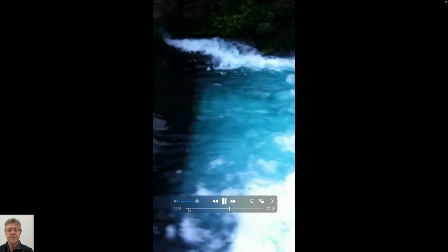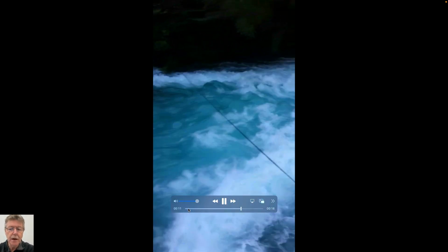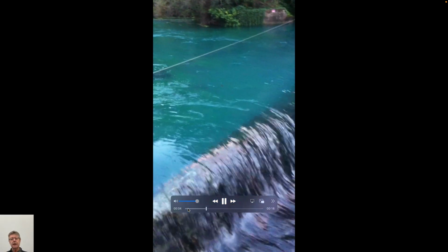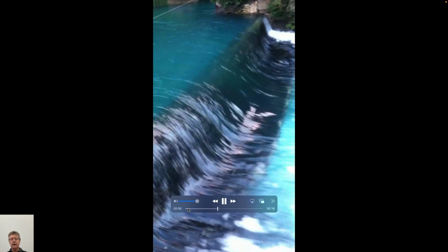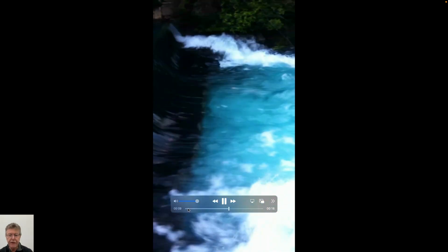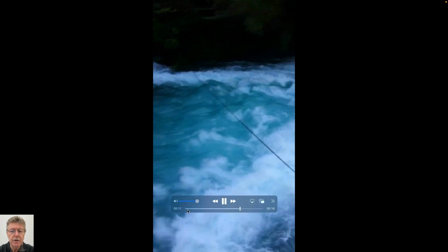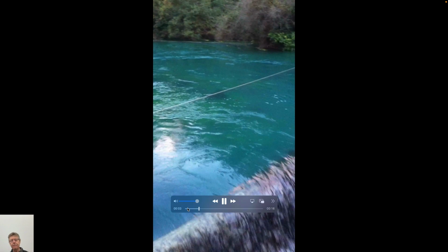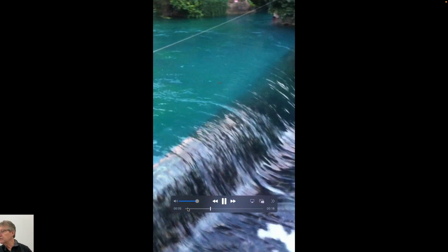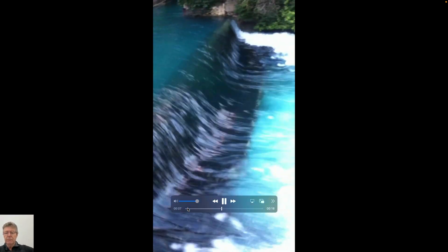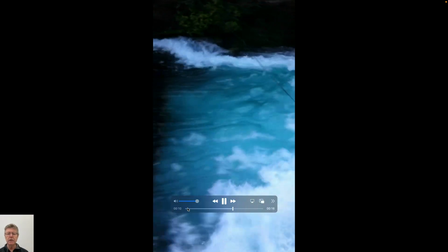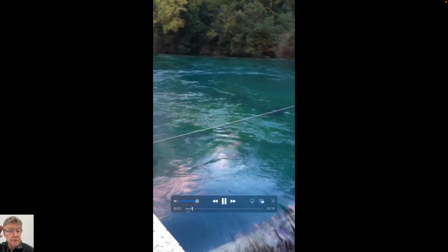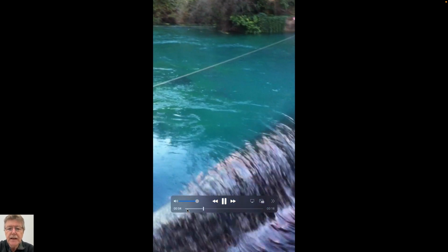As you might know, things like limestone, well, we have limestone around here. All the water supply for State College comes out of limestone. We have these lineaments, which are faults and big fractures in the limestone that have big high permeabilities. They may run for hundreds of feet, thousands of feet, and so they have a large area of fractured rock, which if you put a well in, you're able to pull a lot of fluid out of it. So this is just a natural spring, and I guess this is showing exactly that behavior.